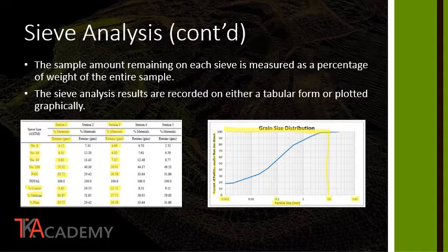Coming down here, reading this chart, we have about 58% of the material passed through the 0.1 millimeter particle size. And all the way down here to 0.01 millimeters, we had about 30. So about 30% passed through that sieve. So we know that they are that size or smaller.